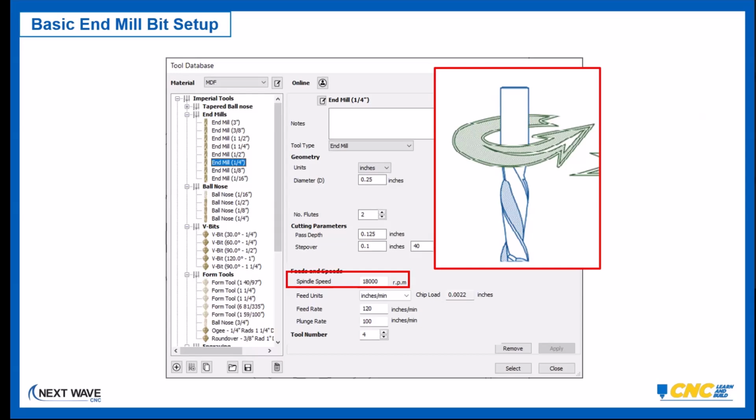Or if you have one of the older Shark machines before they had the automatic spindle control, there are some spindles out there that don't have automatic control on them, and those you also have to set manually at what's called the VFD controller. If any of you have any questions about that relative to your particular machine, you can ask me along tonight or drop me an email. I'm glad to help you out if you need further understanding of that.